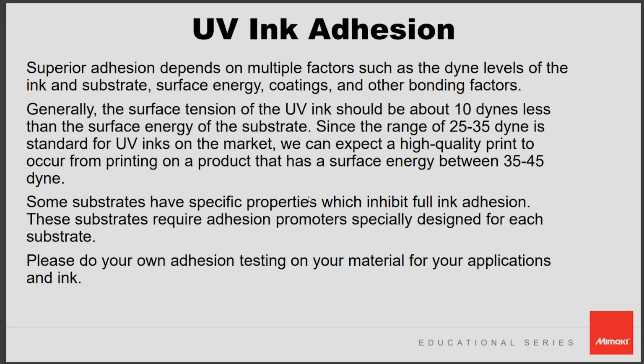The UV adhesion, like I said before, we have the UV ink sits on top of the material. What's great about our UV inks is we also have a jettable primer that we can jet through our print head on a lot of our flatbed printers. And it's really helpful when you need UV adhesion. Obviously, there's a lot of other treatments such as the corona treatment, flame treatments. You can also do wipe-on primers as well. But we also have a general primer that works on most surfaces.